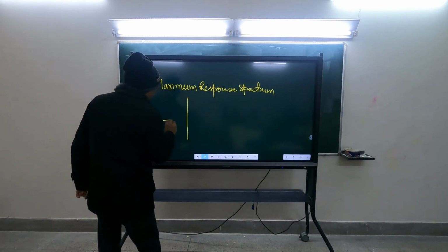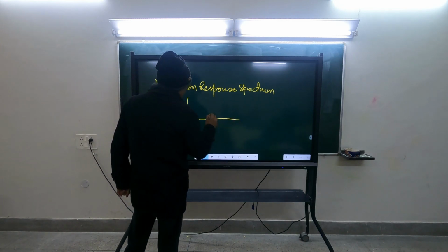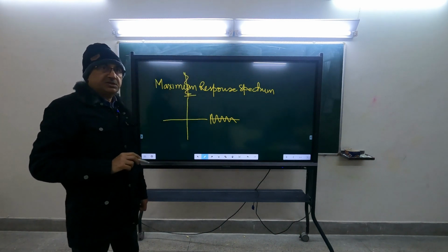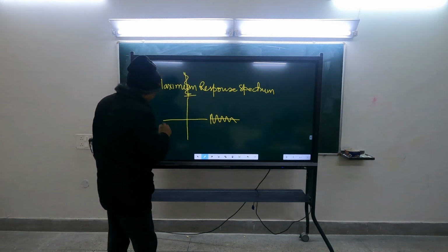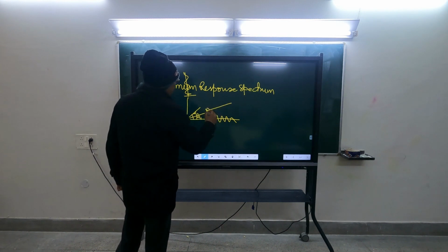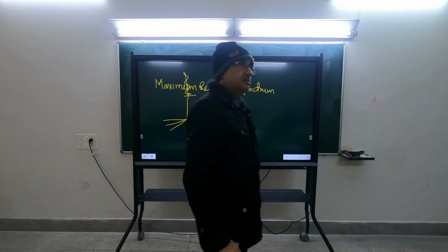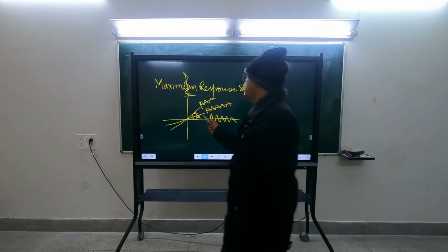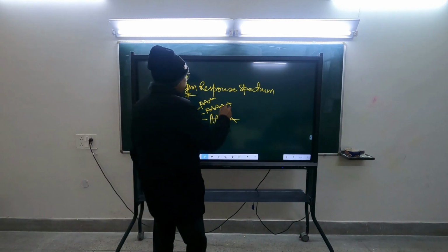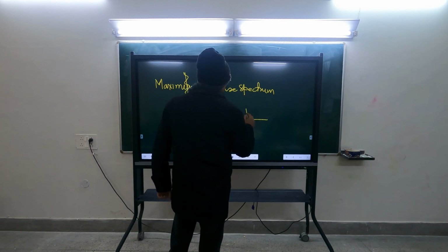How are you going to obtain this? You take the two records which you have obtained from the instrumentation and then consider different directions, these different values of alpha, and then you can obtain the ground motion in each direction. Consider all the directions from 0 to 180, and then plot response spectra in different directions.